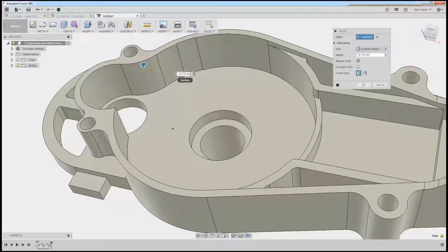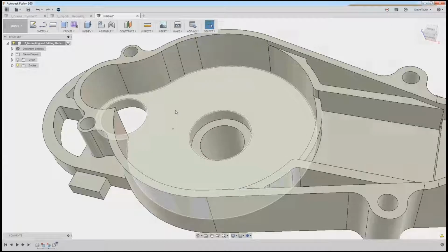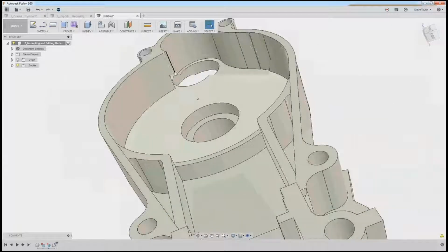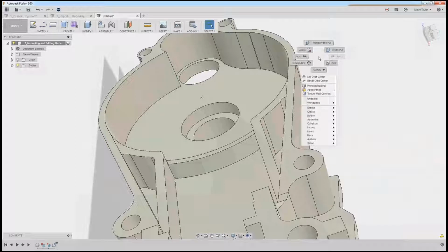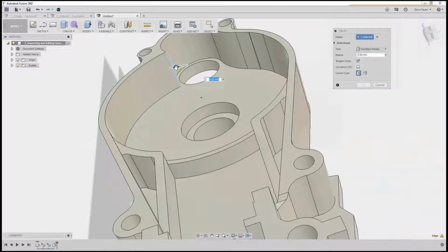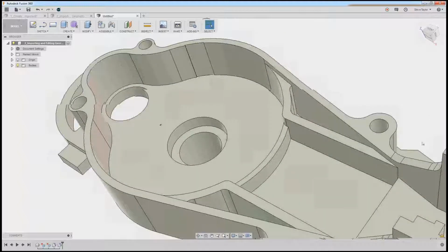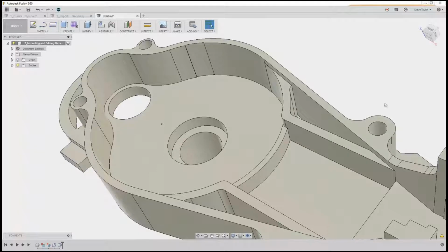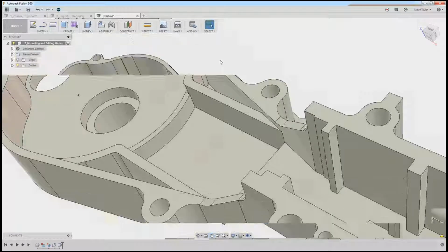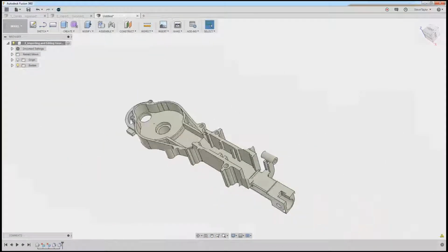So I could actually make that, say, let's see what it looks like at 20 millimeters. It's a nice smooth curve. Yep. Press OK on that, spin it around slightly, and then pick the same edge. Oops. Right click, press pull, same edge, and again I'm doing the same. So I'm able to modify this edge, make it more to what I want it to be. If I then want to move now to the front of this, let's come along there. Let's zoom into the front here.